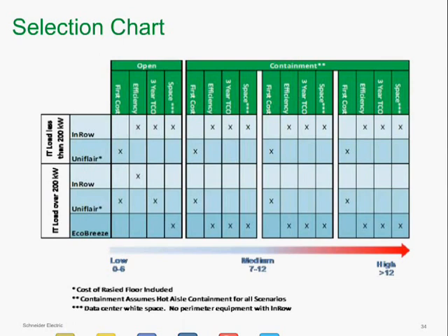of goals in mind. Whereas in a large data center, if you were looking purely at efficiency and you're using containment, we found that a product like our indirect evaporative cooling unit, EcoBreeze, was a great solution. I think across the board, if you're driving almost solely for first cost, a traditional computer room air conditioning unit or CRAC is really maybe the best starting point for you, because those tend to be lower in cost and still provide a pretty good payback on efficiency based on all the upgrades that have been made using EC fans and electronic expansion valves and so forth.